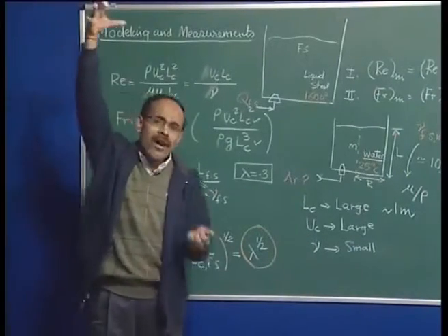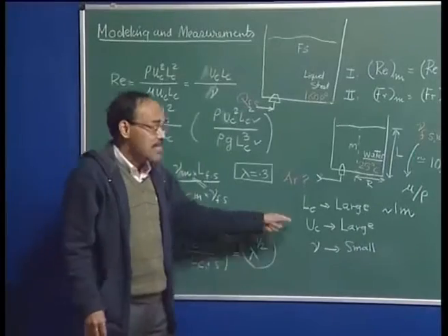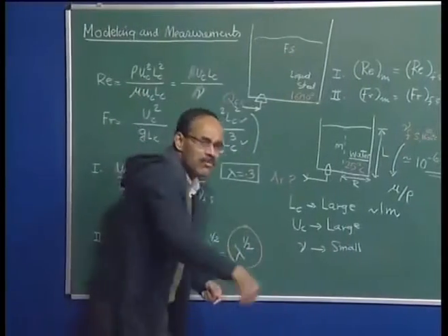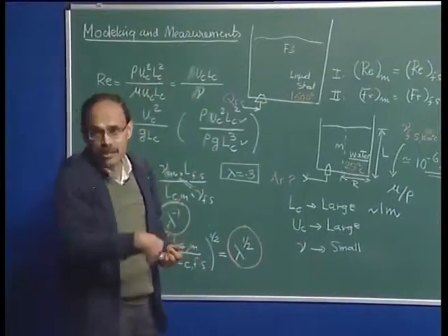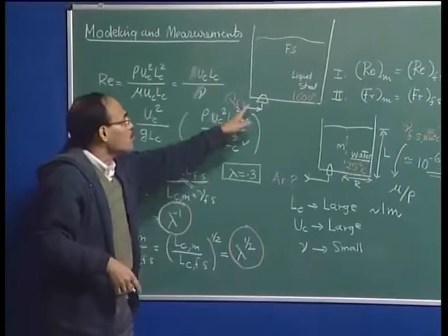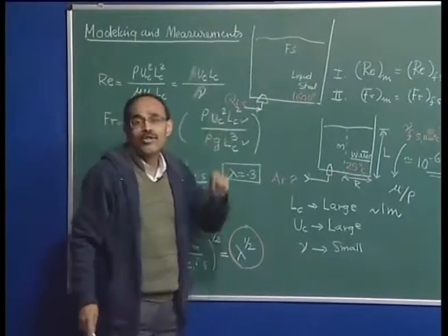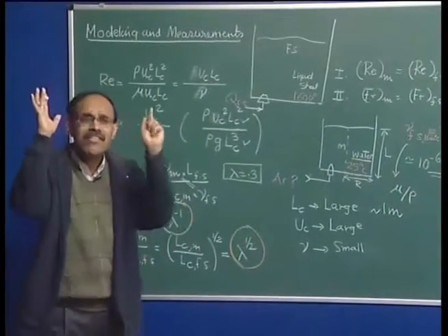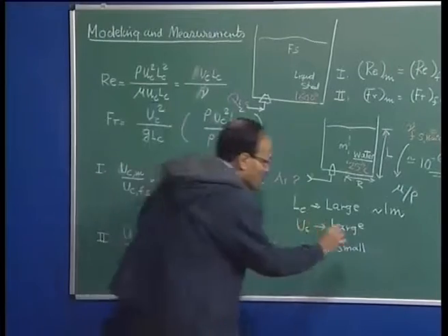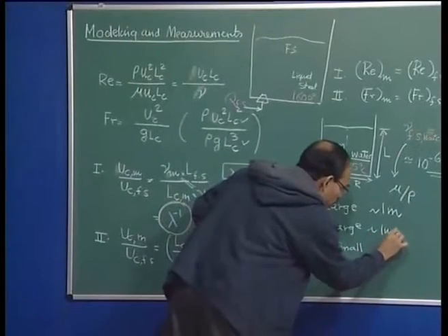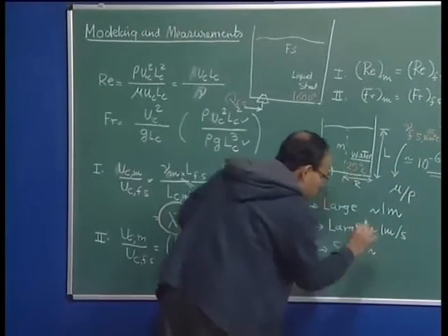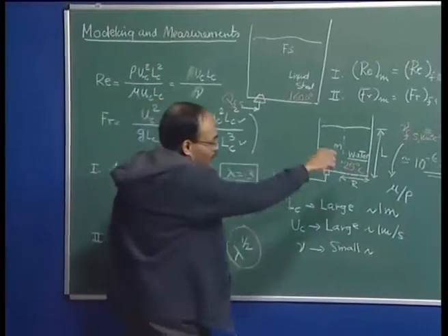For a furnace tapping operation, the extent of stirring in the ladle can be of the order of tens of meters per second. On the other hand, for a gas stirred ladle system with inert gas injection, the velocity could be 1 meter per second. As a first approximation, let us say 1 meter per second, and the kinematic viscosity is small and its value is already given.